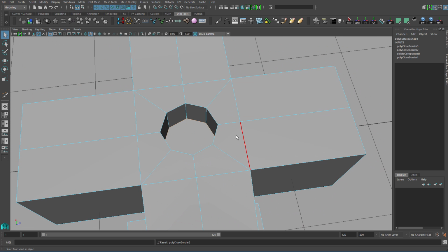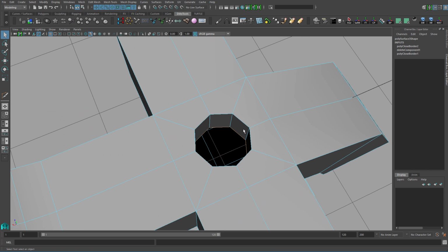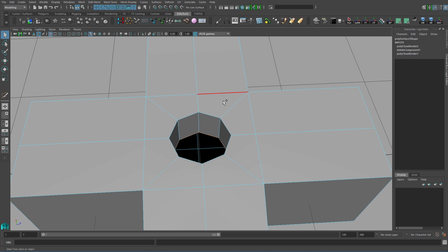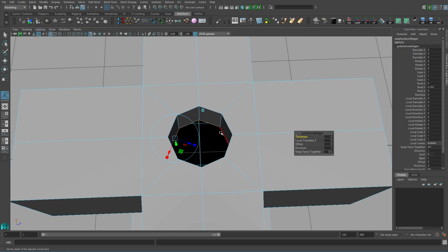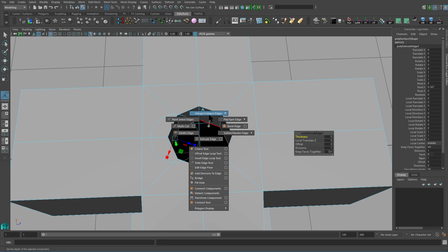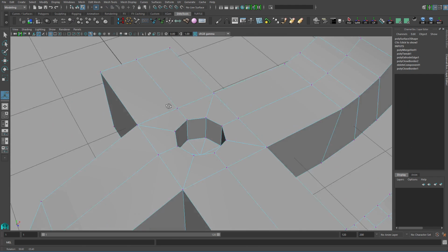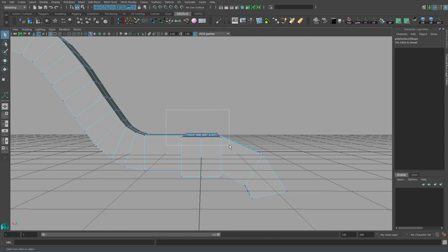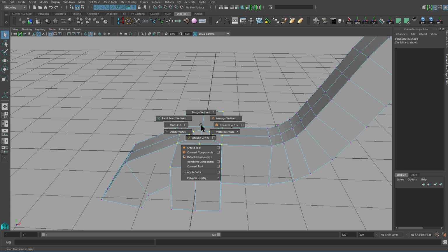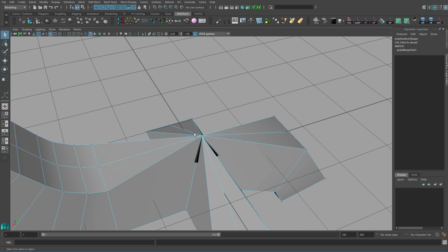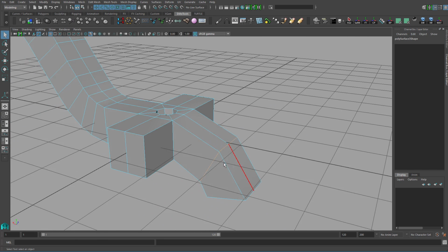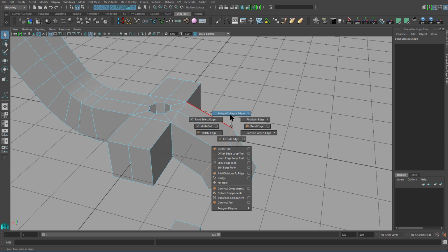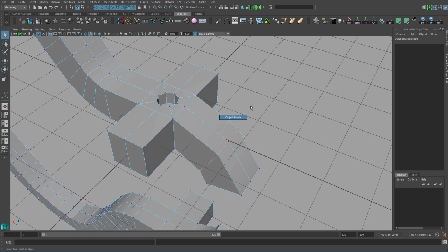I can use fill hole, but I can also scrub all the vertices, all the lines, by double clicking one of these lines on the hole, and I can select all the lines on the hole, and then I can do an extrusion, right? After the extrusion, I can then hold down Shift and right mouse button, go merge, collapse edge, merge edge to center. Now you can fill the hole like this. That actually is collapsing the things you're selecting. For example, if I grab all the vertices and then hold down Shift and right mouse button, go up again, that collapses every vertex into one. If I grab all the edges here, I can do the same command, and that will collapse all the edges into one. Okay, you don't have to wait for this to pop up. You can just go up and it will do that for you.